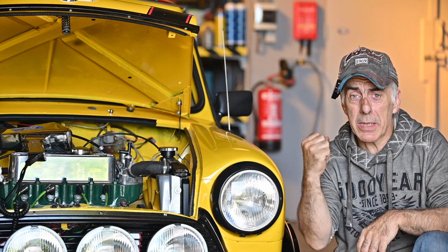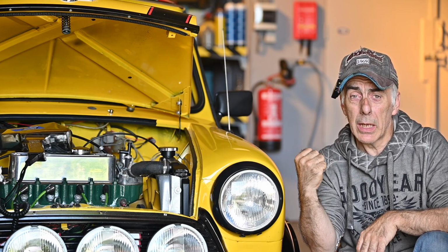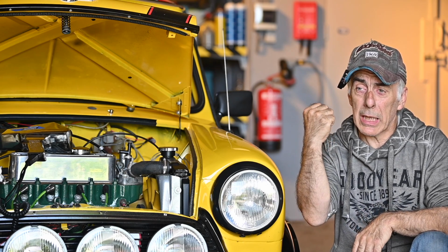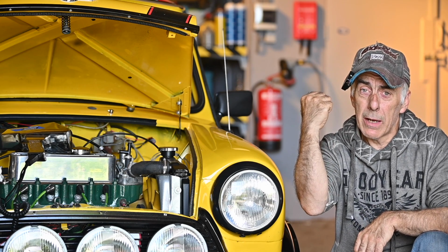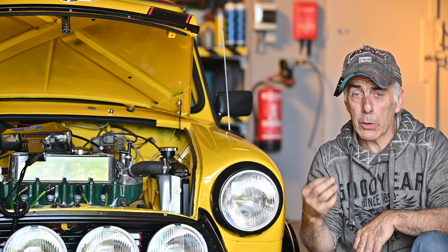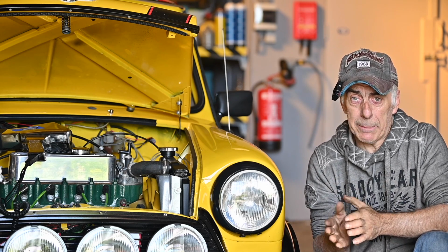We all know that the pistons are going up and down, and if it's a four-stroke, the piston will suck in air and fuel through the carburetor when it's going down, and then it's coming back up, and now we have the compression cycle. And when it hits the top center, that's the moment in time we want to push it violently back down by causing an explosion of the air and fuel mixture by igniting it with a spark.